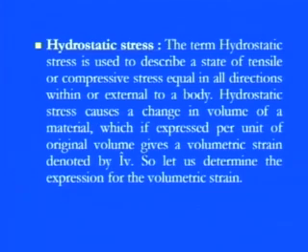If the state of stresses is tensile or compressive and they behave in an exactly equal, isometric way in all three directions, then we can say these are the hydrostatic stresses, and hydrostatic stresses cause a change in the volume, because they go equally in all directions. So whatever change comes, it will come in a volumetric way.